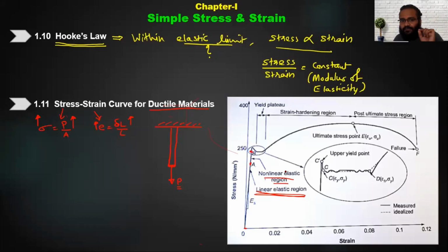After the elastic region, after that elastic limit, if you go beyond that elastic limit, after that wire turns into plastic zone. Wire turns into plastic region, or we also call it as strain hardening region, where the wire will elongate up to a certain limit but cannot be regained 100%. Complete regain is not possible. Okay, understanding it? So once you overcome the elastic limit, उसका वायर का कंप्लीट रिगेन करना पॉसिबल नहीं होता. इफ यू अनलोड इट कंप्लीटली, तुमने पूरा का पूरा डिफॉर्मेशन फोर्स निकाल दिया, फिर भी वायर में कुछ ना कुछ परमानेंट डिफॉर्मेशन रहेगा. ठीक है, मतलब वो ट्रेसेस रहेंगे.